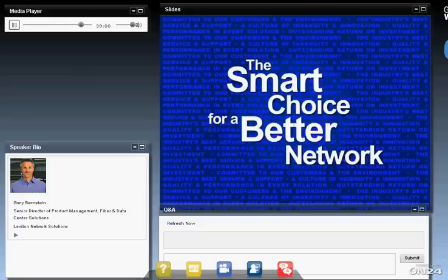We tend to agree with you. We think if we can plan in advance and get the lengths, it's a lot easier to have these trunk cables terminated in the factory and then delivered based upon the schedules that are provided with the proper lengths. However, I have seen MPO pigtails. I can't remember who had them, but I've seen pigtails that you can splice. That is another option. You could fusion splice those pigtails in.